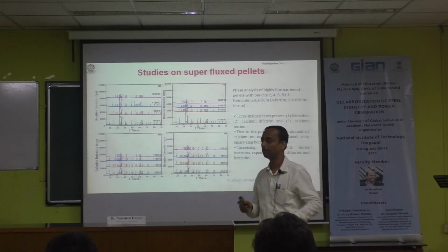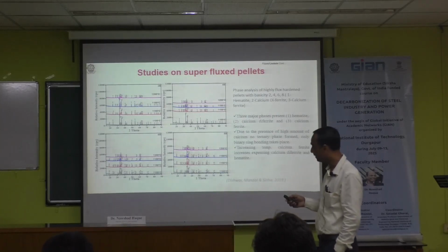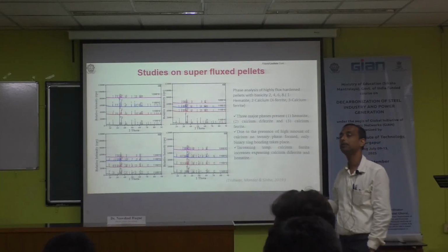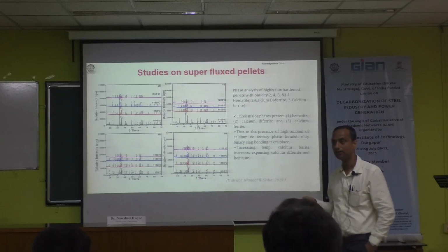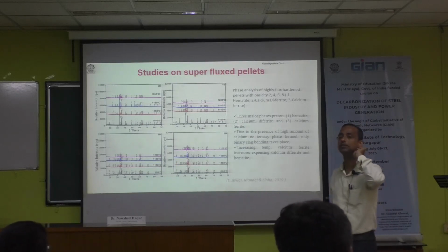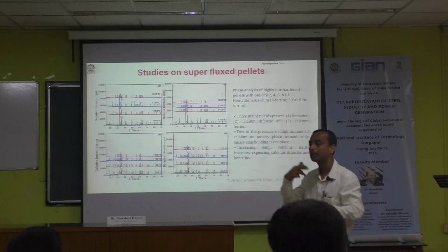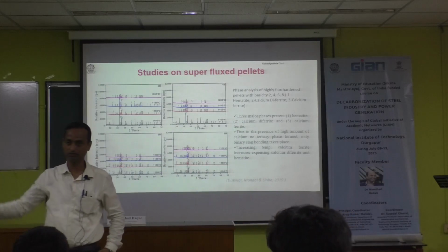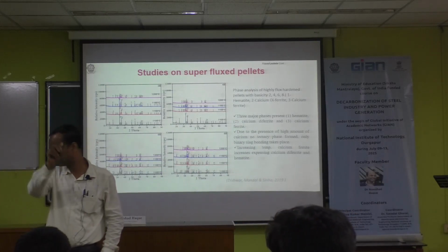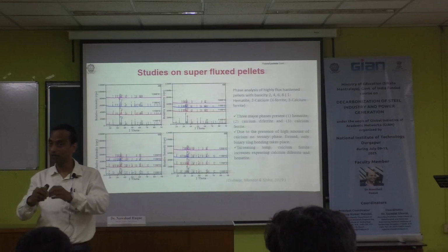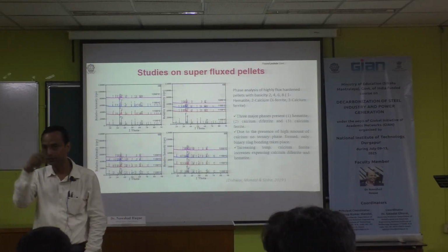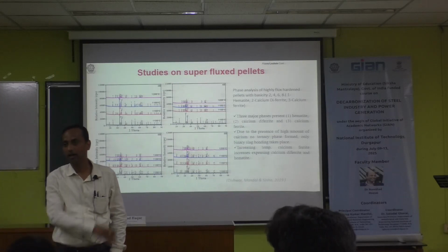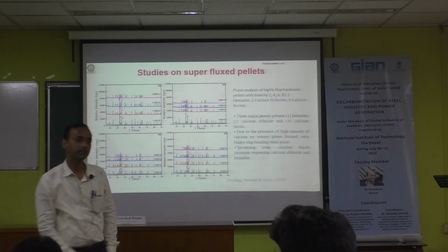But precisely you have to control it. Depending on the different temperatures, you have different basicity requirements. You have to replicate this type of pellet, and you have to choose the optimum temperature so that my plant will not have any clinker formation. Clinker formation: if slag comes out, it will form a clinker. It will form initially a spread layer inside the kiln, and after that the layer will move in this way.